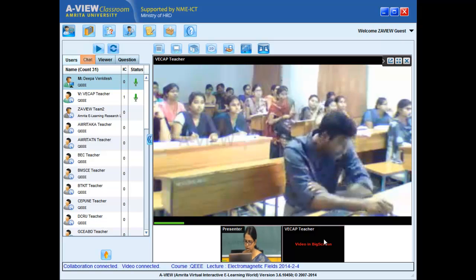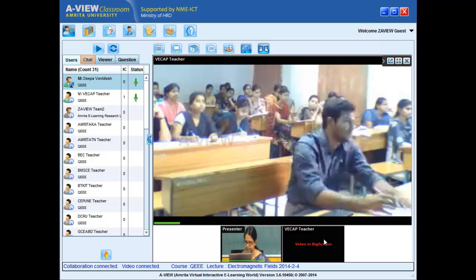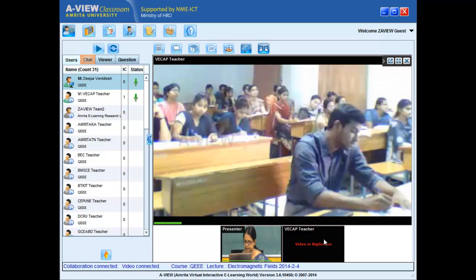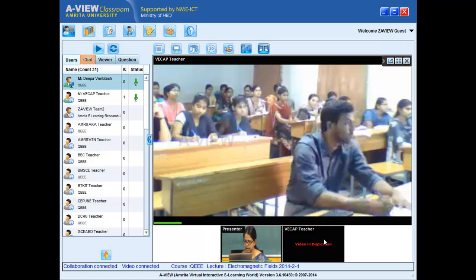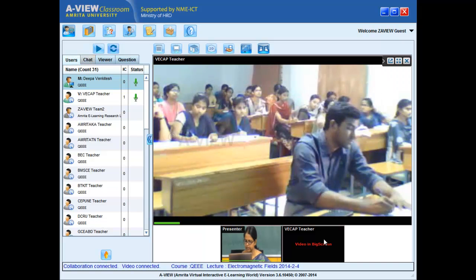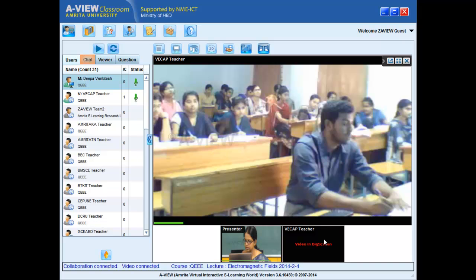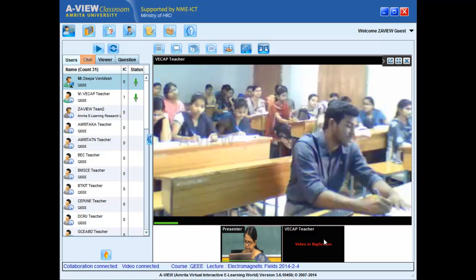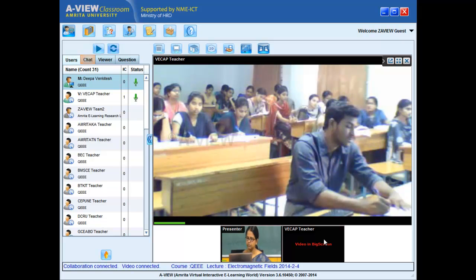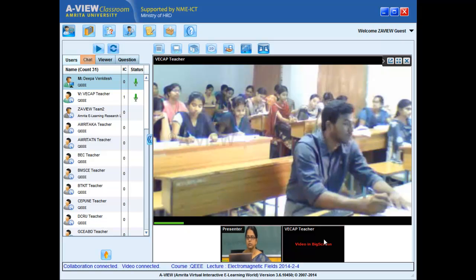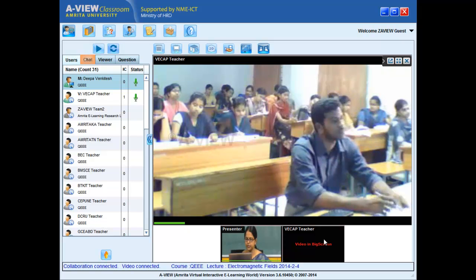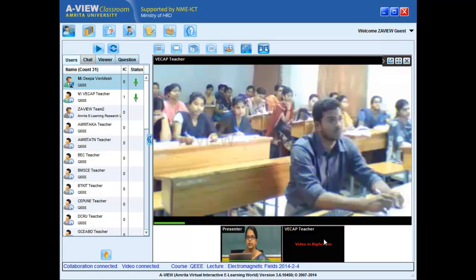I divide throughout by delta Z, and on the right hand side I have R I(Z,T). I have divided out the delta Z, so L delta I by delta T, function of Z,T. This is purely from Kirchhoff's law. I have not done anything special here.